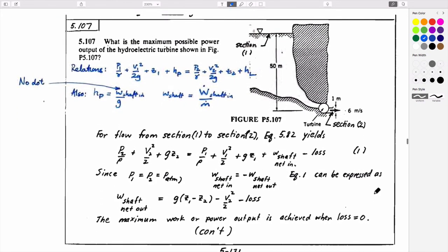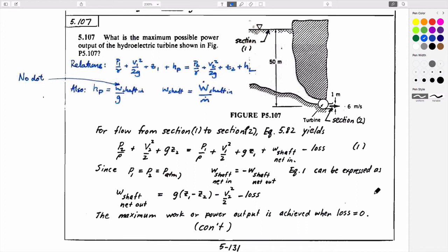Energy is also recovered that way, so pumped hydro and hydro schemes. The idea is that you run water through a turbine. It turns the turbine and adds work into the turbine, which is that this is negative. So turbine is negative when we look at the Bernoulli equation. When you collect water here, you pump it back into the reservoir, so-called pump storage schemes. One of the big issues with renewable energy is its intermittency. You get power when the sun shines or when the wind blows, but you need to even it out for demand, and you need to store it at night when it's not used. And so one way you can do that is you can pump water up the hill so it has some potential energy, and then you run it back through the system after the fact.